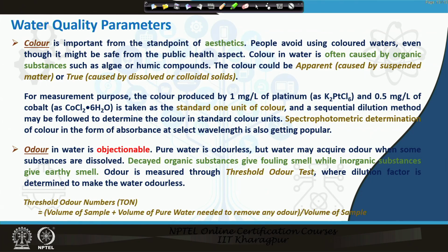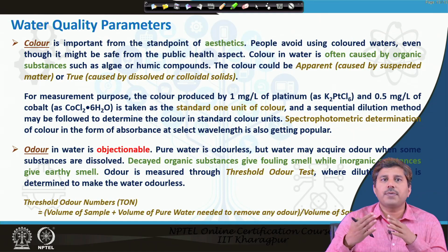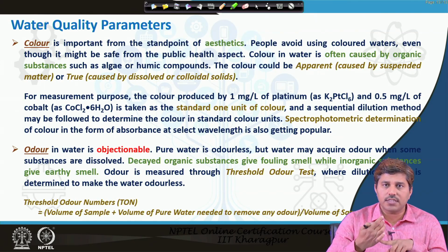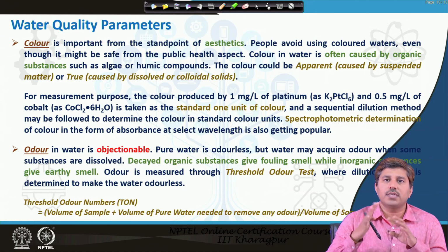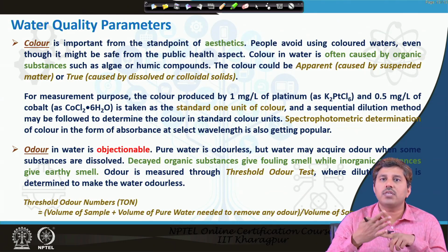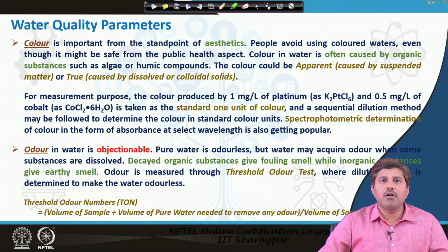So, conductivity is taken as an indirect measurement for various other parameters, which includes the total dissolved solids, because it is proportional to the dissolved salts. So, we can have an indirect assessment of total dissolved solids using conductivity or salinity. Okay. So, salinity can also be measured using conductivity, because that is also a form of the dissolved salts. So, the salinity or TDS also can be measured through the electrical conductivity. Okay. Generally the conductivity meter that we have, the conductivity probes, in the other mode they will be able to give the direct value of TDS or salinity.